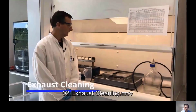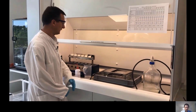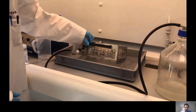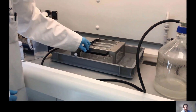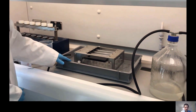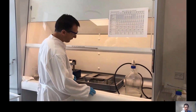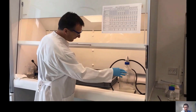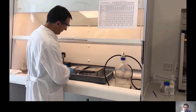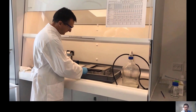whatever you like. So now I'm going to show you how to clean the exhaust from the digester. I've taken out the exhaust from the digester here and put it in a plastic beaker, and within this there's hot water. For effective cleaning of this and removal of most of the acids, you can use this system. It's a water aspiration pump. You have a flask here for trapping of the liquid, and you need to connect the exhaust by doing like this,